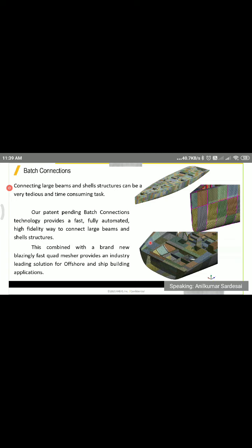But in such cases, like in CFD we discussed, I have not said anything in lakhs. I was speaking in millions. Right? Let's say 50 million, 80 million, 100 million, 200 million, and so on. So in CFD, it's a practice to have the mesh in millions. But once it comes to mechanical or structural, you try to reduce the mesh count.